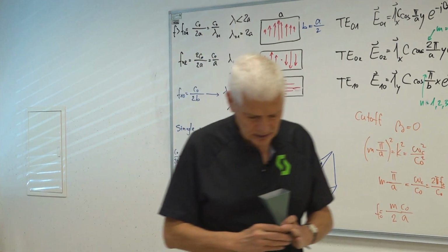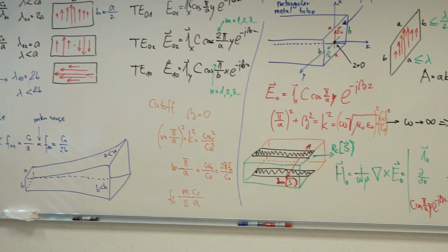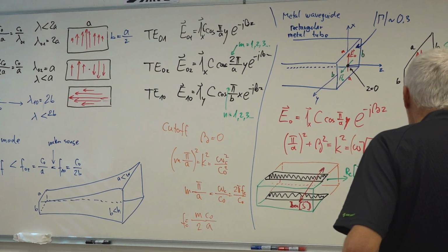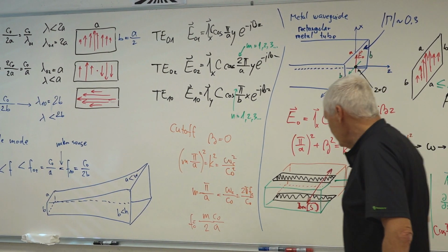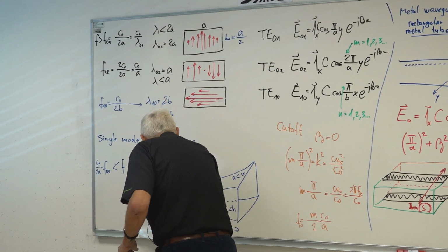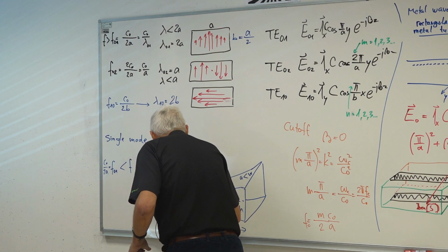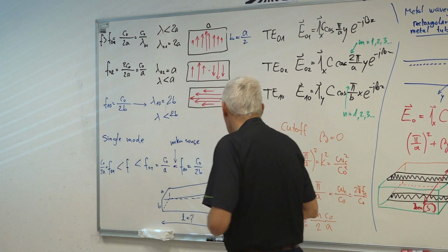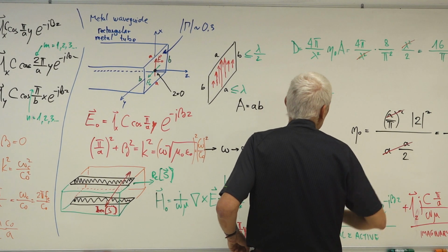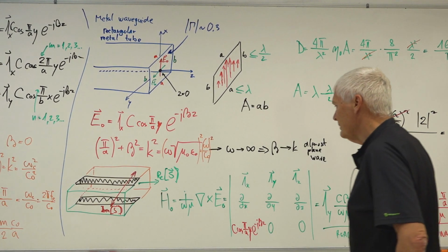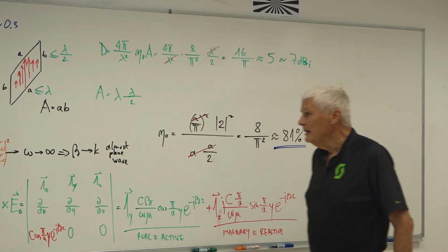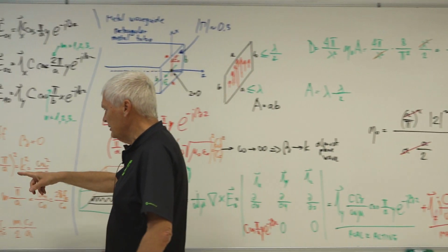that has a very, very smooth transition. Also this one here has the waveguide to coaxial cable transition, and then we have this horn that is slowly increasing. So if this thing is long enough, and how long it has to be, then I should be able to obtain higher directivities, higher effective areas here, with still approximately the same illumination efficiency. So where is the limit with such a horn here?